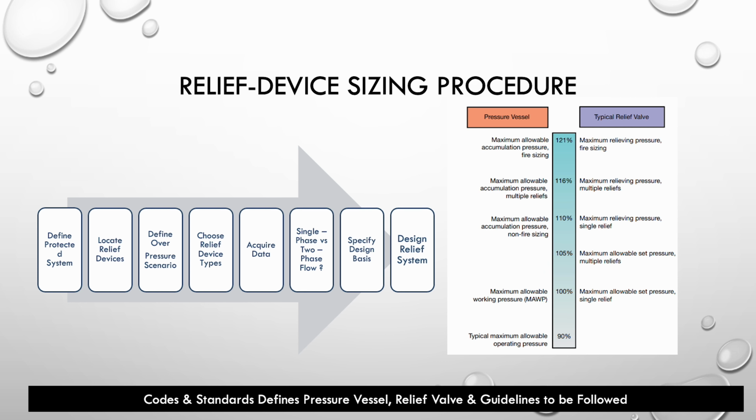Because HAZOP or SIL classification might go through so many revisions. Right. You don't just do the HAZOP one time and it's just over. Some updates will be taking place, and whenever updates take place, you're going to need to revisit all these documents to make sure that they are not introducing a new hazard that hasn't been already accounted for. Right.